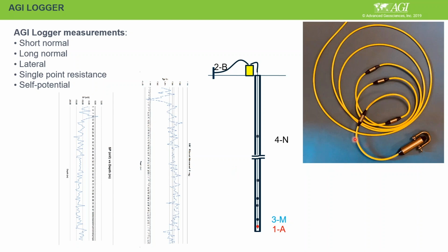When you have this logger cable, we also send this command file and all these related measurements, and they just lower down your cable to the depth interval you want to measure. But this measurement location will be in the borehole saturated zone. Okay, so the borehole either has mud or water. The unsaturated zone you cannot measure, so it can only be the saturated zone.